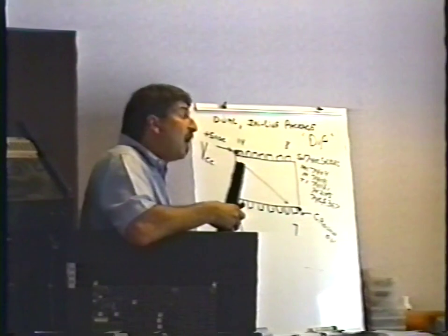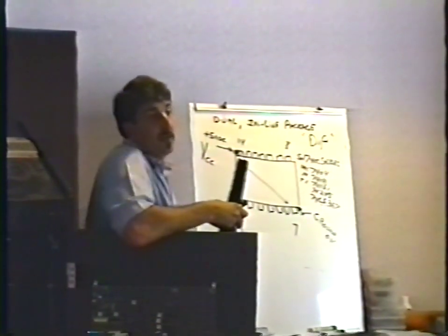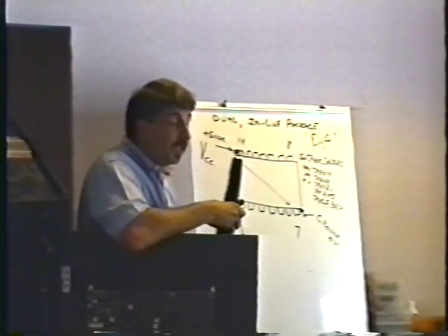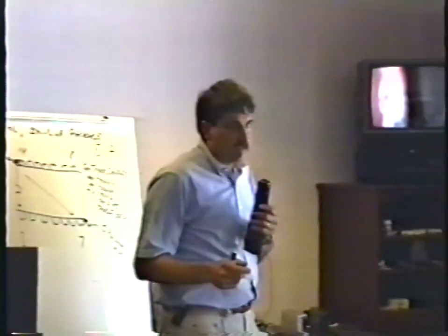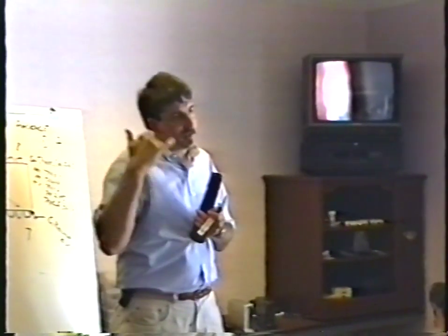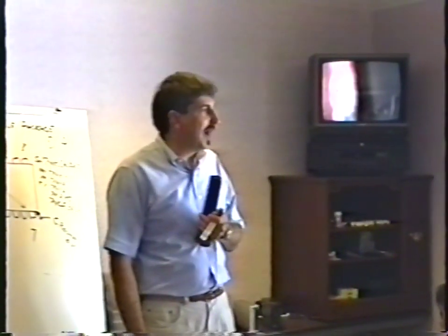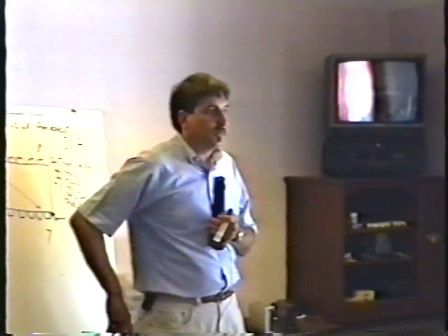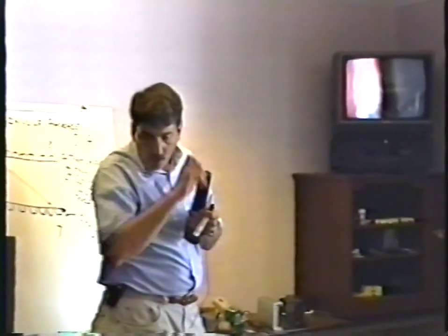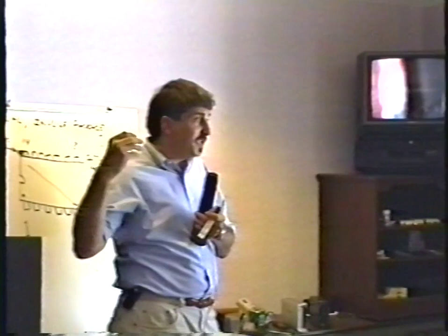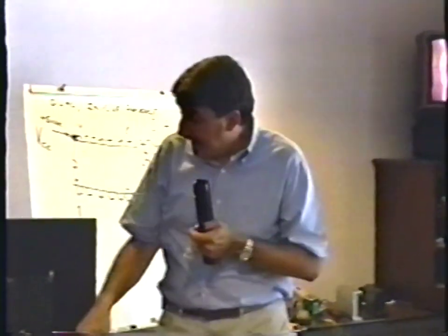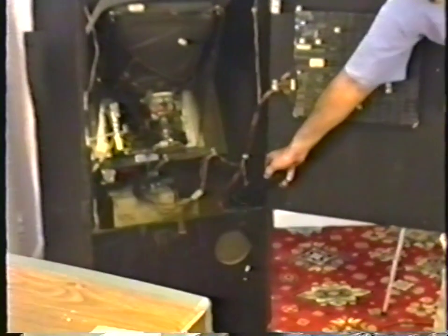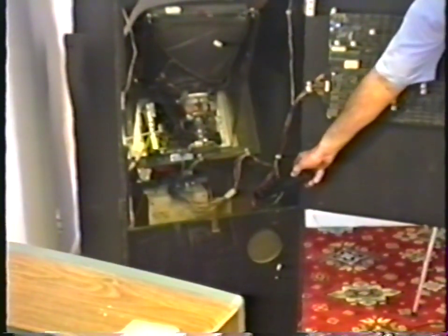This is the number 1 cause of people sending their boards into the distributor for repair when there's not really anything wrong with them. What happens is someone gets to the game and let's say the game's doing some kind of wacky things like shutting off intermittently. You get this complaint, the location says, yeah, the game just froze up or whatever. They turn it off, you get there, you turn it on, of course it works perfectly okay for you. Or weird bits of graphics and weird jazz on the screen, all this kind of stuff. This may just simply be a power supply problem. And what happens is people measure the voltage down here at the power supply itself, down here on the inside, set it to exactly 5 volts.